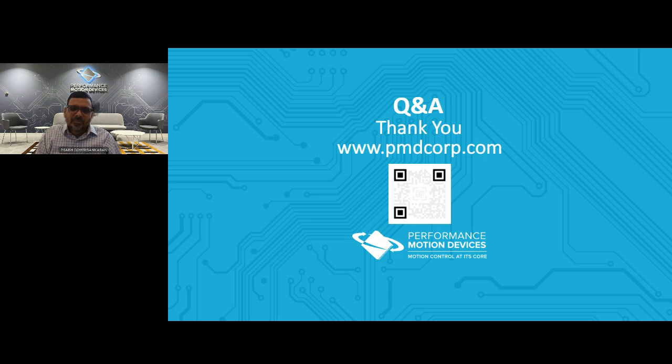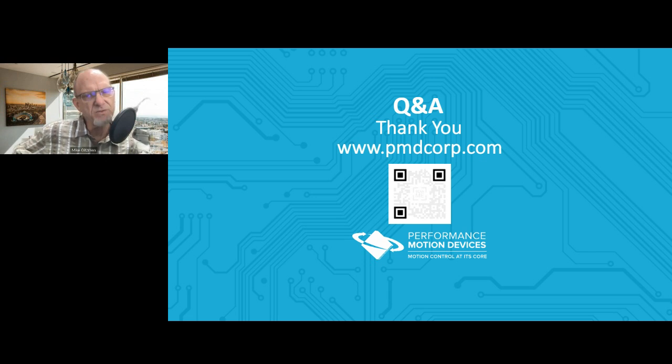Interesting. So there was another question, I think you sort of answered this, which was synchronizing motion across multiple axes. That would, certainly in the case of either distributed or centralized motion control, you're still synchronizing set points, trying to get all the axes to work in coordination with each other. In the case of a mobile robot, the motors for the wheels starting and stopping at the same time. Is that correct?